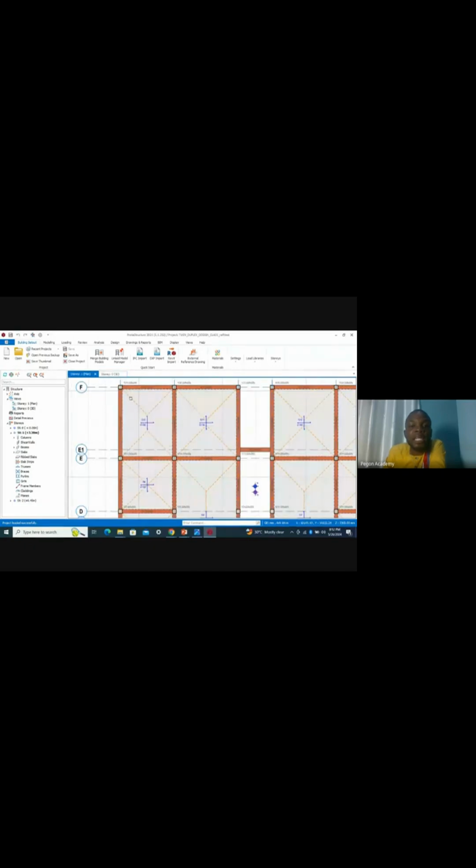So if you look at this yield line, it simply tells us how the load is transferred. You can see this triangular part, the load is going to the beam. This trapezoidal part, the load is going to this beam. This trapezoidal part, the load is going to this beam, and this one is going to this beam. So this beam is simply carrying the load of this trapezoidal part and this trapezoidal part together, and they are all transferred to the beam. Now, in addition to the dead load of the beam, the load is divided into 2 and transferred to this column and to this column. Right? Now, the same thing applies to this one.